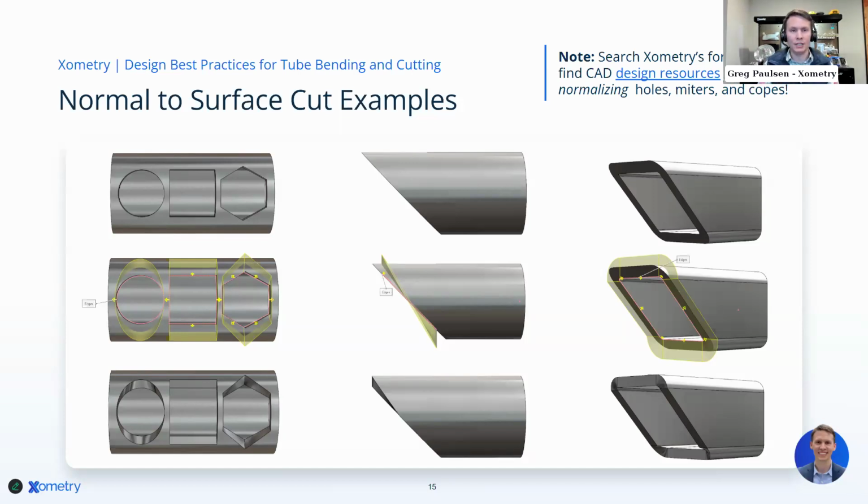By the way, a lot of times if you're receiving tube, and Tim, we talked about this the other day, when you're adding these together, a lot of times you are either grinding or creating tube features, so you have a space to weld it into. So you kind of see on this design here what that looks like. Yeah, especially for welded applications, it provides I guess a prepped fitting for good joint penetration.